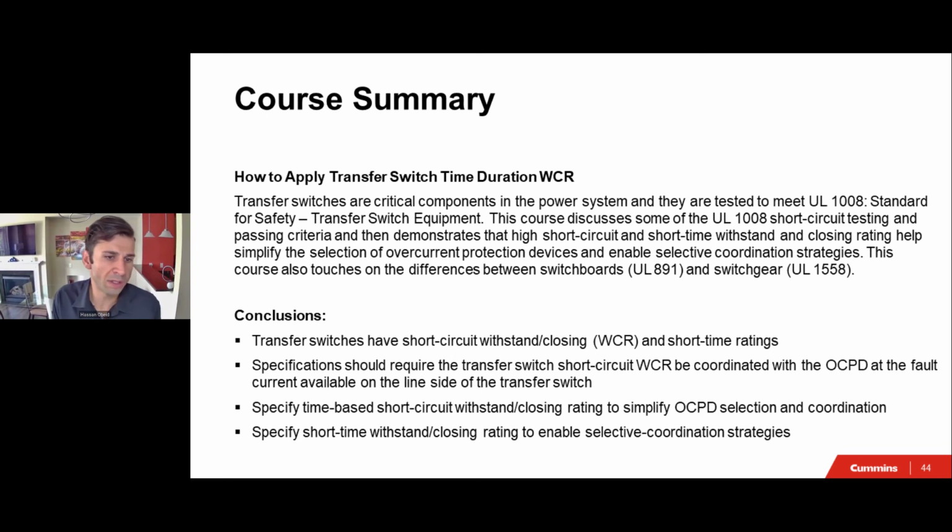Specify time-based short circuit withstand and closing ratings to simplify the OCPD selection and coordination, and specify short time withstand and closing ratings to enable selective coordination strategies. I hope I was able to demonstrate that throughout this presentation.